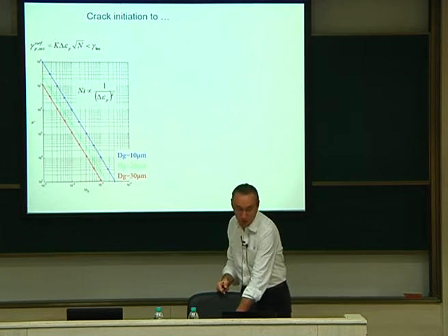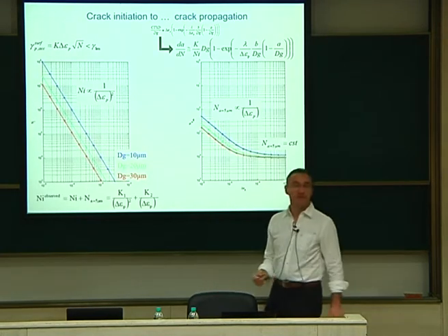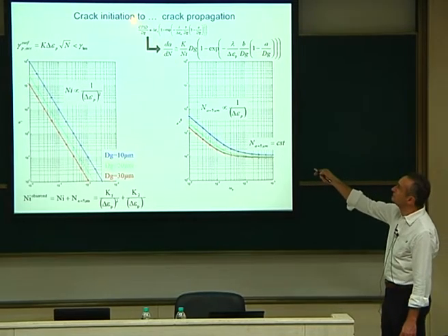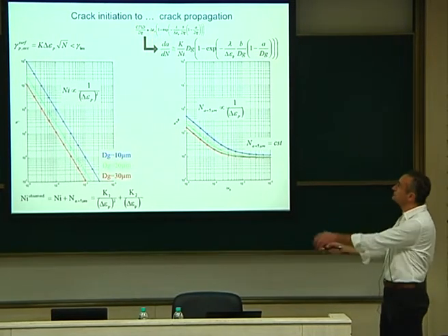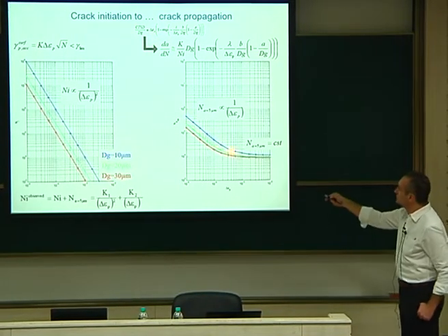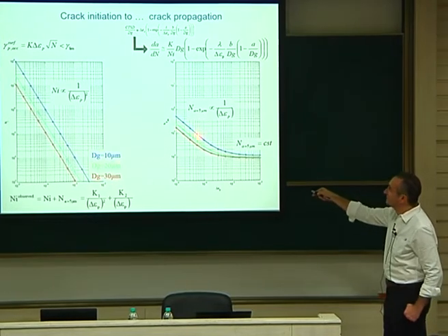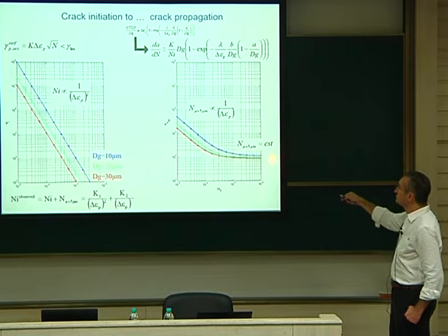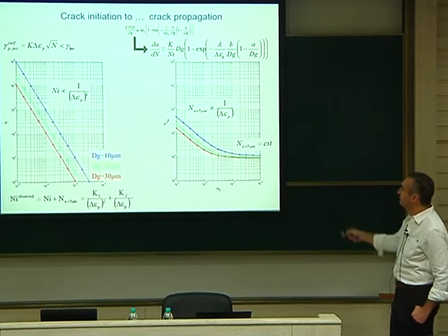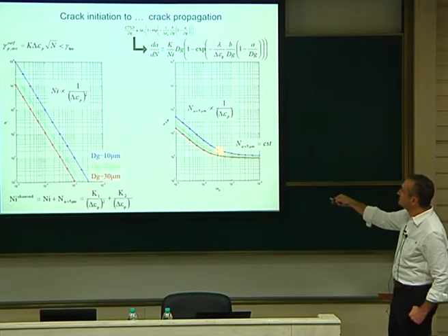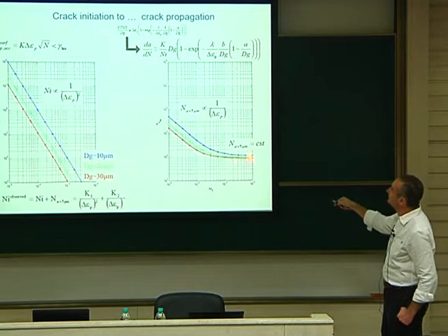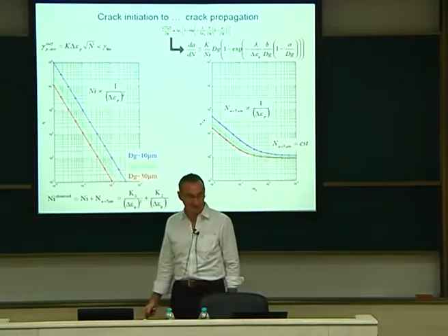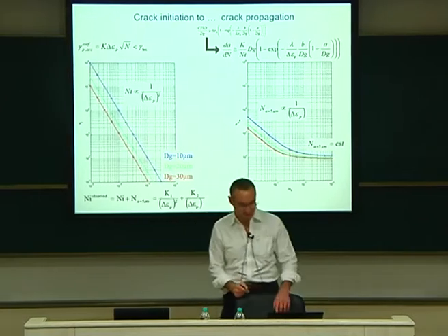Now if you superimpose to that the propagation stage of the crack, it follows this exponential law, like that. You can assume that this is similar to the propagation velocity of your crack. And this looks like this. You have something which, again, depends a bit on the diameters. Those three diameters are plotted there. And you have something which is slowing down for this amount of deformation, okay? So this is the crack advance, which depends on the grain size and the plastic strain amplitude.